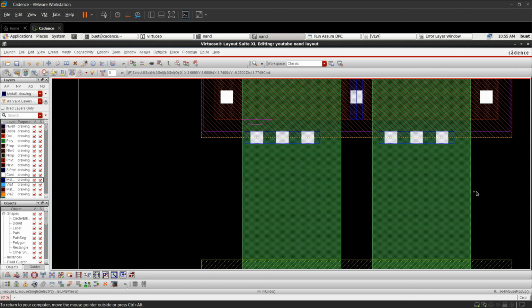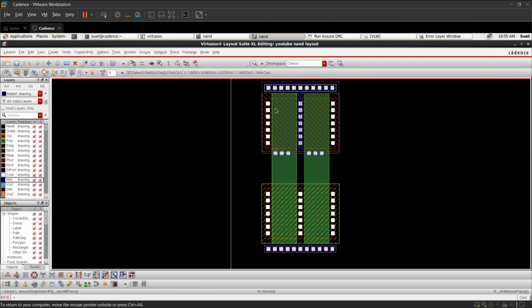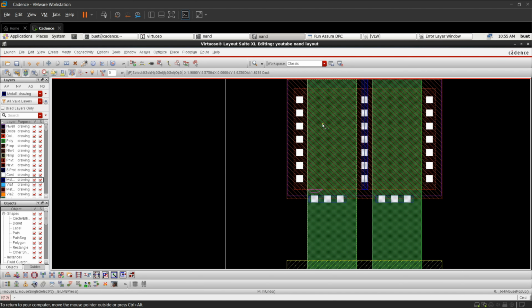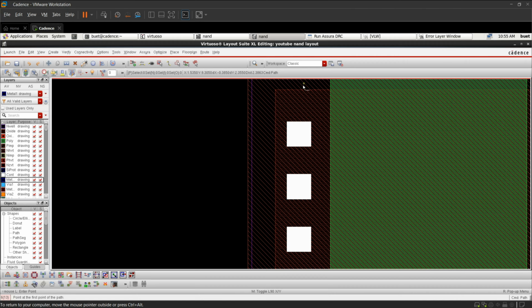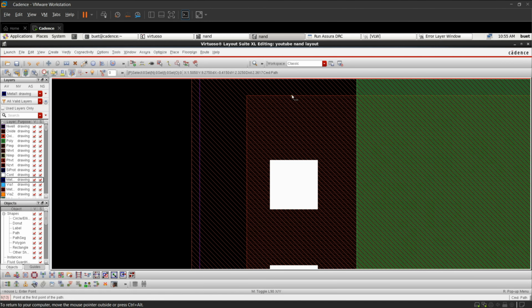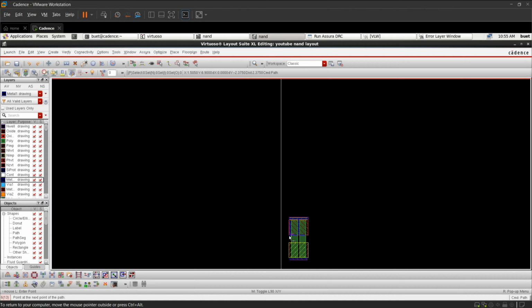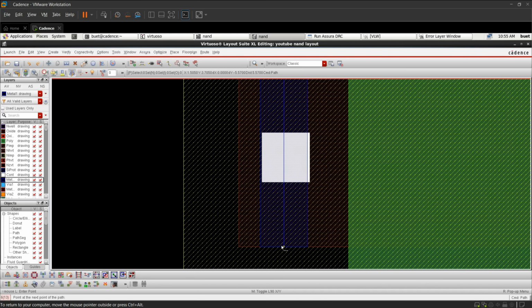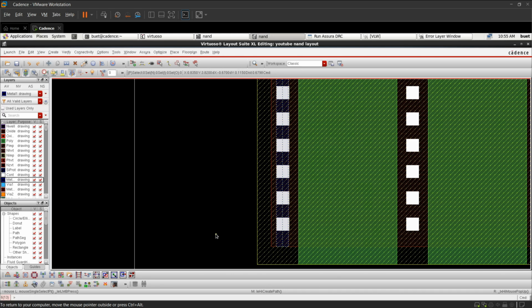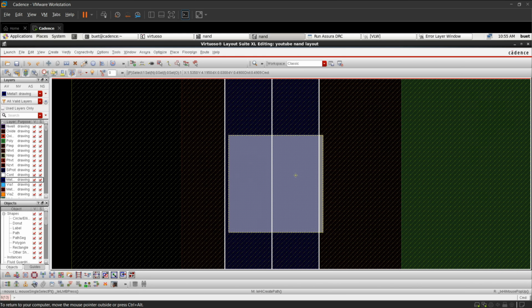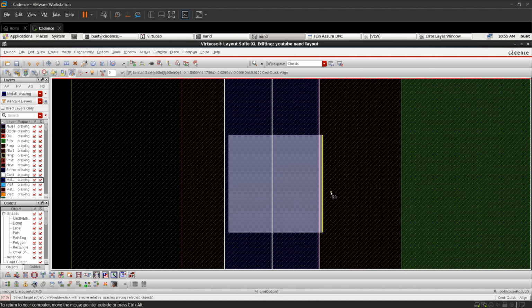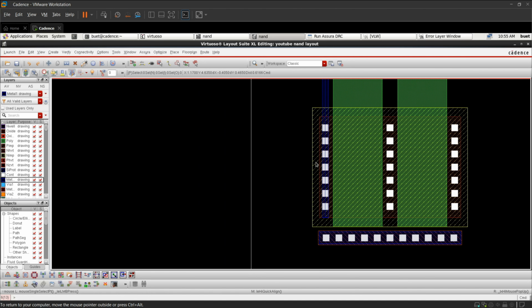But here we are going to get our routing also. We'll see what's the spacing between metal to metal. Just route this, press P, select this drain of PMOS and just connect it over here. Just press enter. Okay, align this with our contacts, select this, align, spacing should be no spacing, select this edge with respect to this. Yeah, it's done.